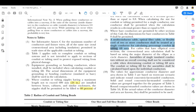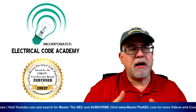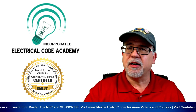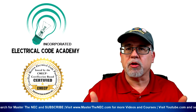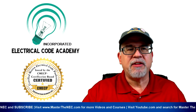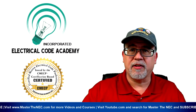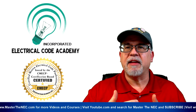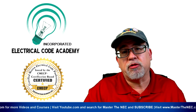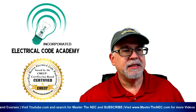What does that mean? Well, that means if I take an MC cable, or I take an NMB, non-metallic sheathed cable, I can put that in a raceway. Various articles for those wiring methods do permit it, and I put it in there. Then I treat it as a single conductor, and I take that cable and treat it as a single conductor. As a result, the raceway fill is 53%. So I can't exceed 53%, so I treat that cable as if it's a single conductor. And that's how we apply it. All right?